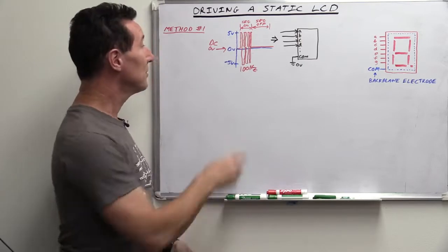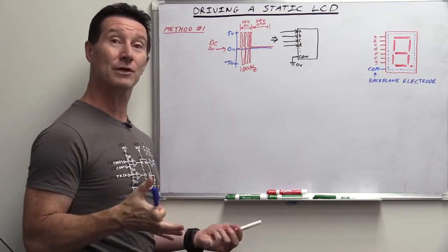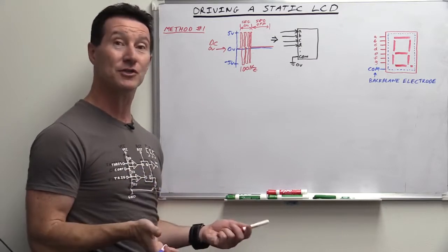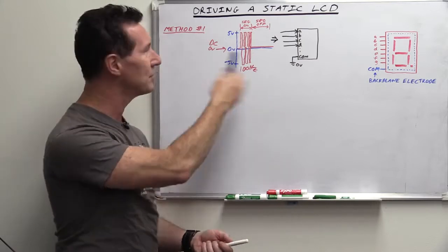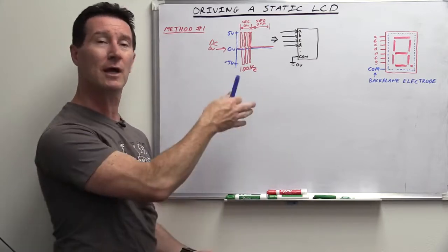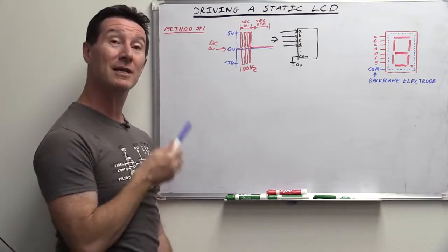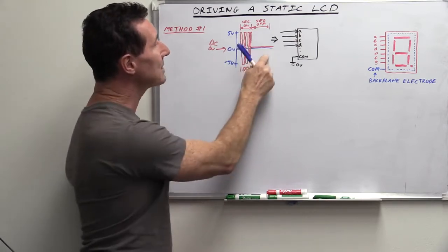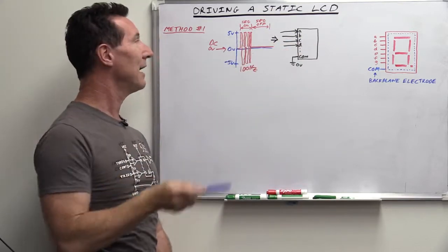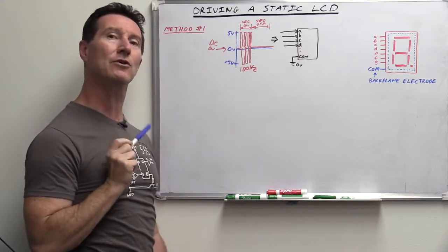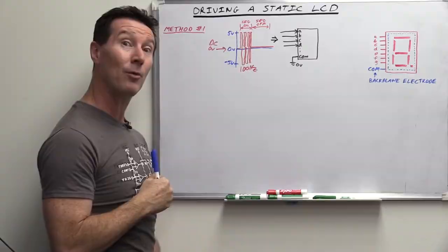But the problem is you've got to have a negative 5 volt rail down here, and that's going to ruin your day if you've just got your digital logic, your 3.3 volt digital logic, 5 volts, you've got an Arduino or some other microcontroller and you just want to drive your LCD. Getting that minus 5 volts is a pain in the butt. Anyway, let's go have a little play around with this on the bench, and then we'll come back and show you a more elegant solution to solve this problem that doesn't use a negative rail.